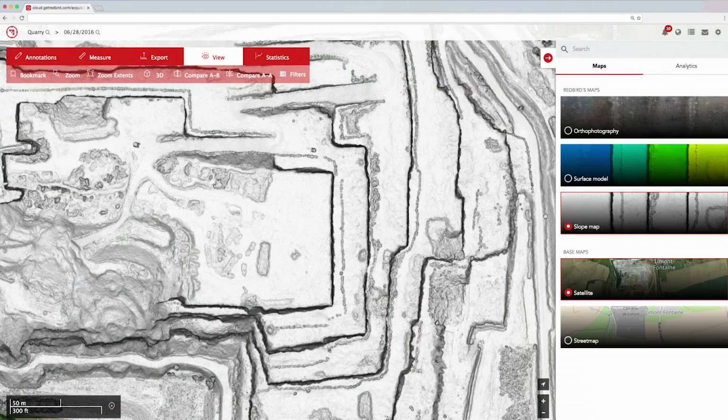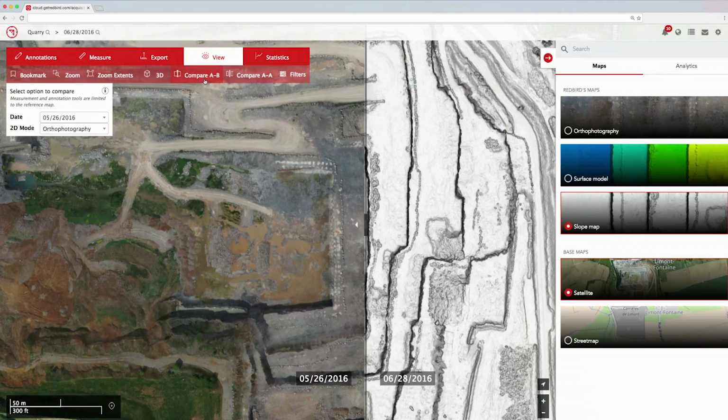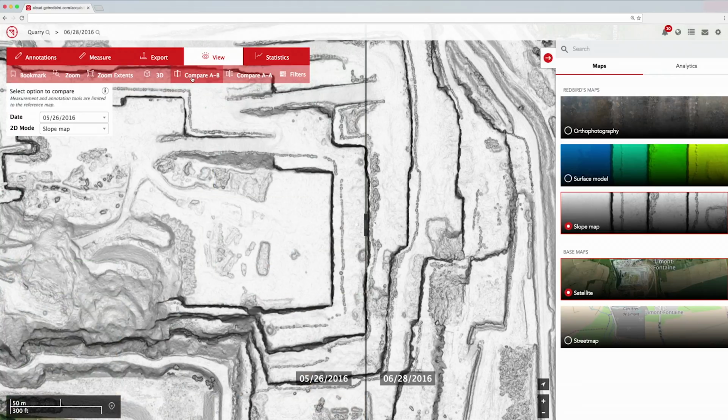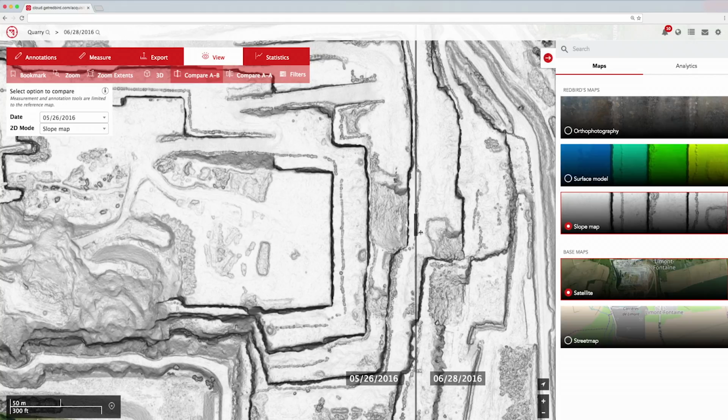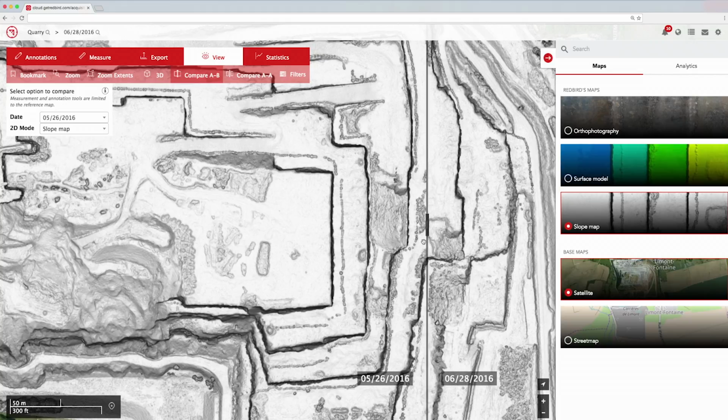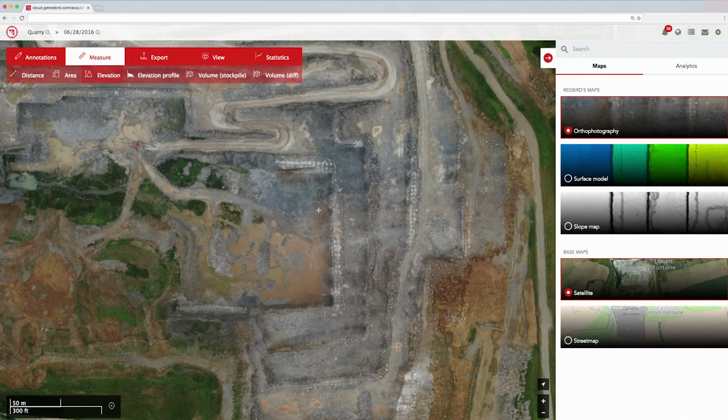You can also view a 3D digital surface model via a hillshade map or slope map, which you can see here. The density here is about 1,500 points per square foot, or even higher. That's 100 times more than traditional surveying methods on the ground. You can get accurate northing, easting, and elevation values from any point on the map.